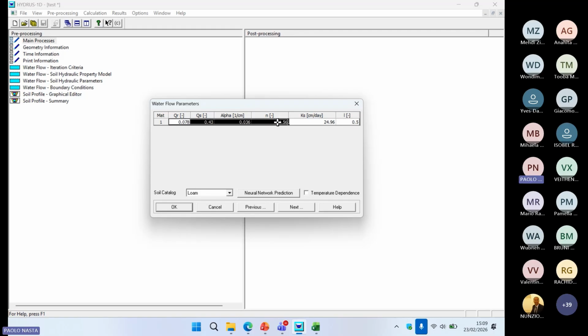So basically, as I said, we have the options. We either collect the soil sample, take it into the lab and determine the soil parameters, or we optimize the parameters directly by using field data, usually soil water content and pressure head values, for the calibration of the parameters. Or, if we are desperate, we use easily retrievable soil physical or chemical properties.